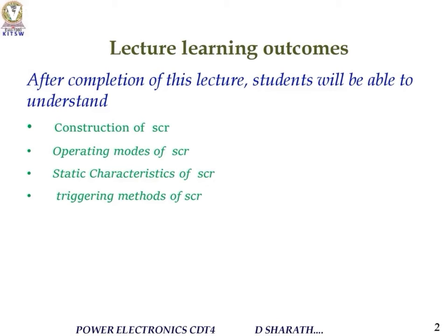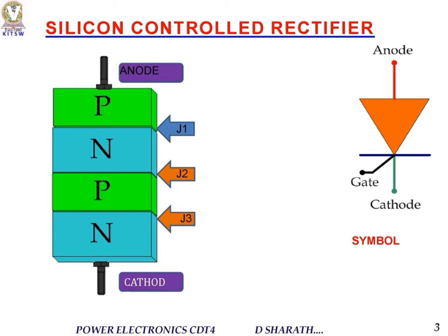In this lecture, we are going to study these topics: construction of SCR, operating modes of SCR, static characteristics of SCR, and also triggering methods of SCR. Coming to construction of SCR, SCR is a four-layer, three-terminal, three-junction device.